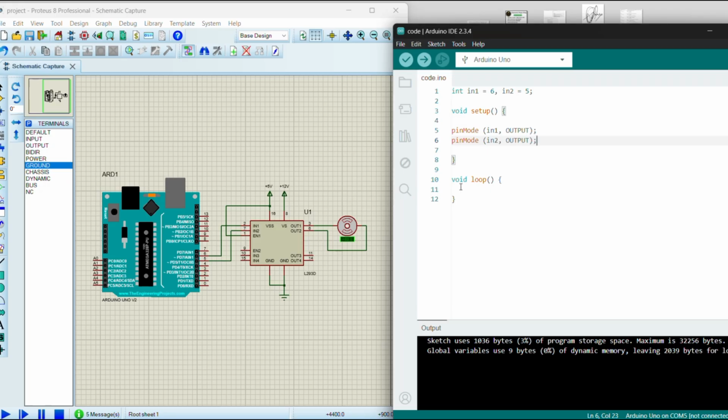And once we are done declaring the pins as input and output, we will be able to control this particular motor when we talk about the rotation and direction. If we want to have the motor operate in a clockwise direction, then we can write the code respectively. And if we want the motor to operate in an anti-clockwise mode, we can also program it by giving this specific instruction. It is mostly defined as sending a signal to each of these inputs of the H-bridge.